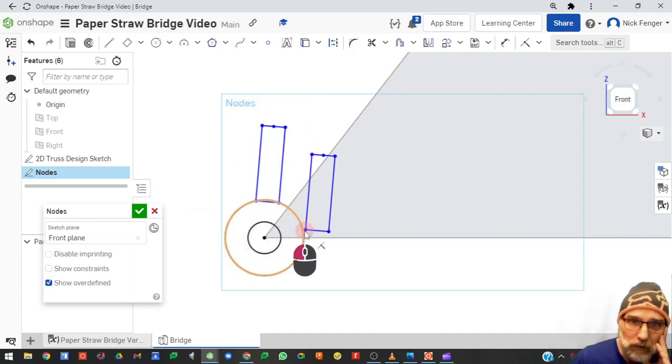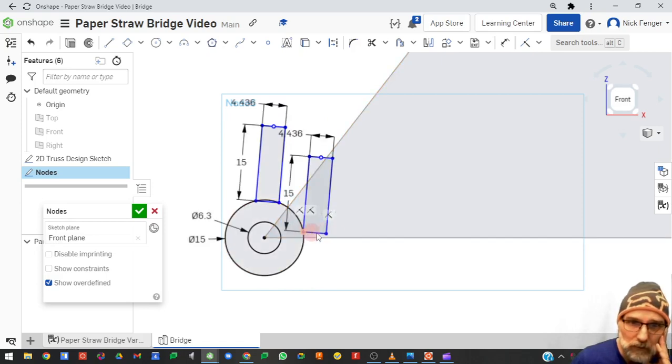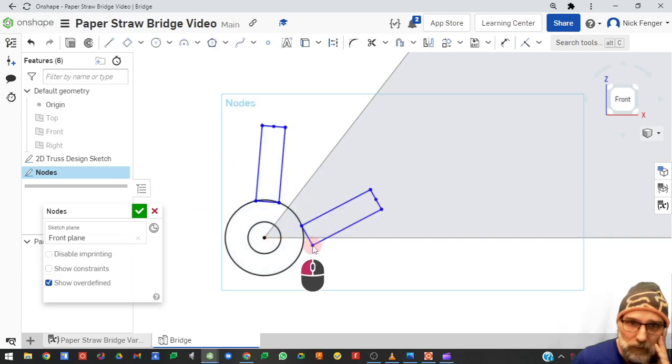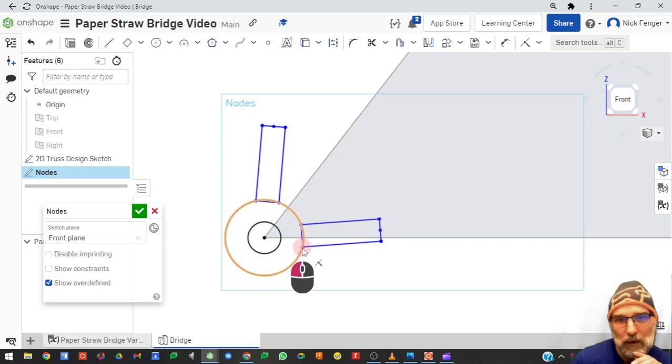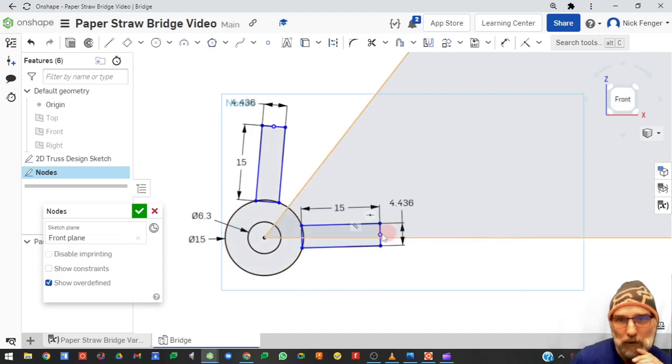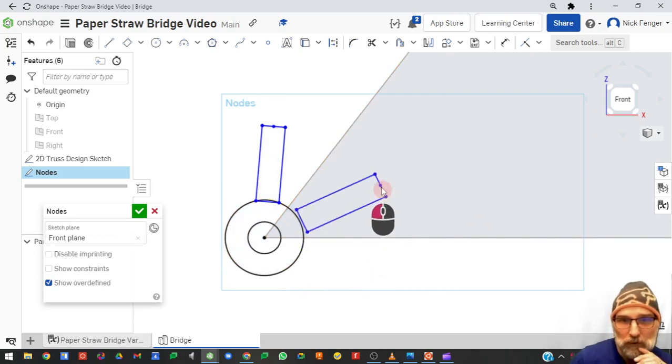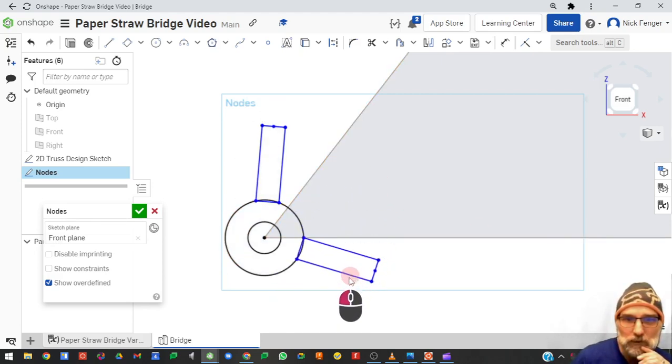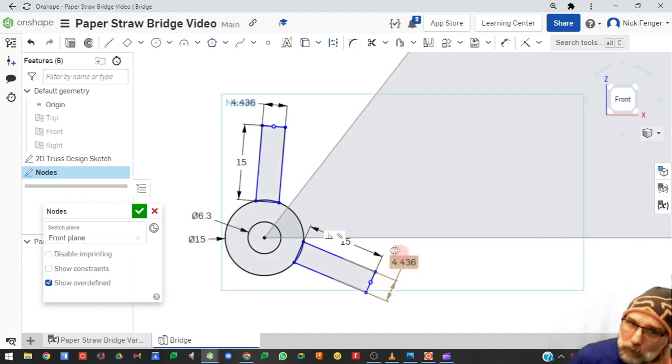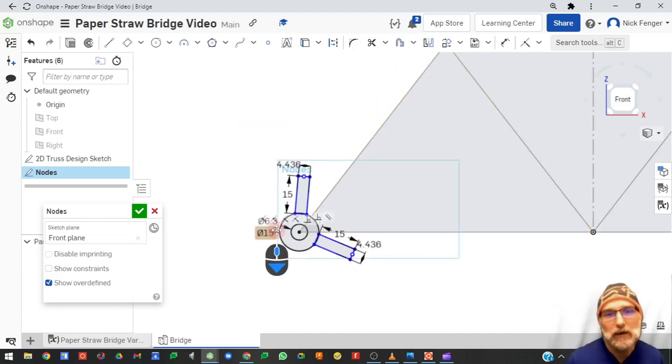We're going to move it down here. I don't want it to go too close, so we're going to go here. That's going to create a coincident onto there. Notice now it's stuck on there. And we're going to bring this down here and just create a coincident. Make sure you're only creating a coincident. If it's starting to make parallels or 2 coincidents, move it a little bit. Okay, so now we have another one, and you can test it again. It should do this. Okay, so we've got 2, this is what we need here.